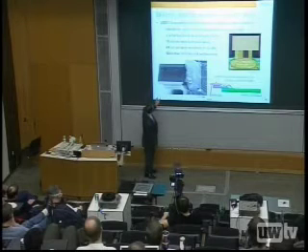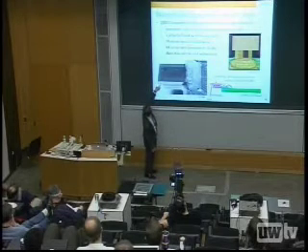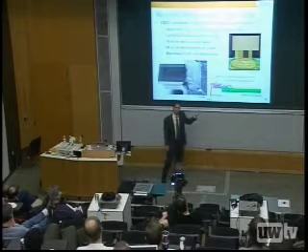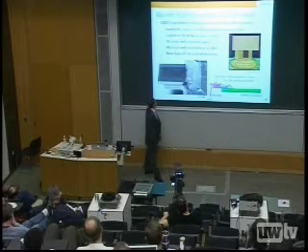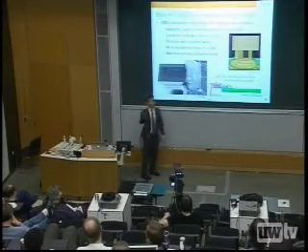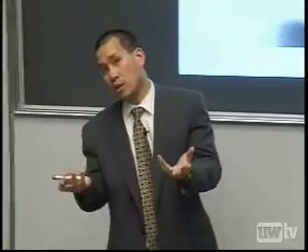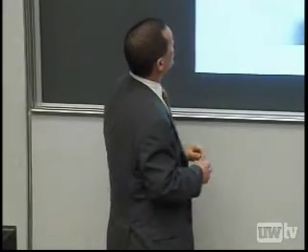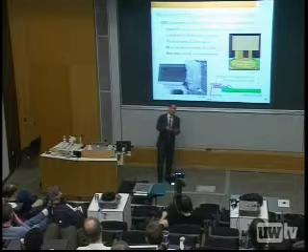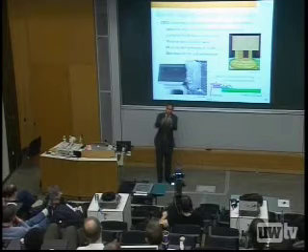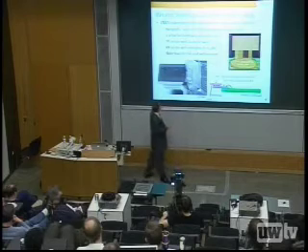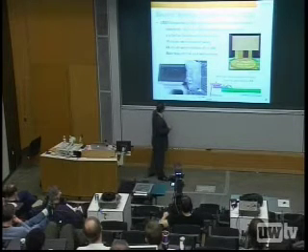And so what do we get? We got about 1 picojoule per bit for the transmit plus the receive. That doesn't include tuning power or laser power, but if you add those in, it's about 1.5, maybe 1.2. The transmit circuits are a 2-volt modulation swing on a ring modulator. And the receive circuits can do a sensitivity of negative 15 dBm. That's about 30 microwatts of received power. It's a relatively small signal that we can transform into a 1-volt swing, at a bit error rate of no more than 10 to the negative 12.